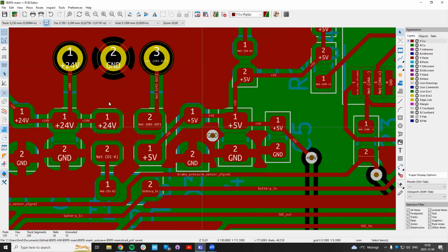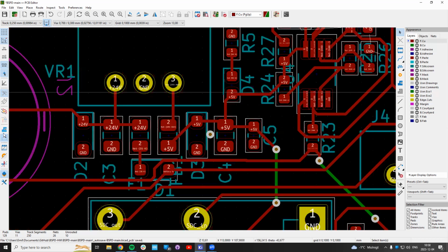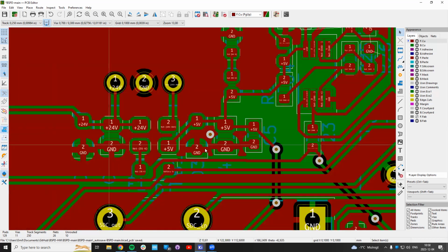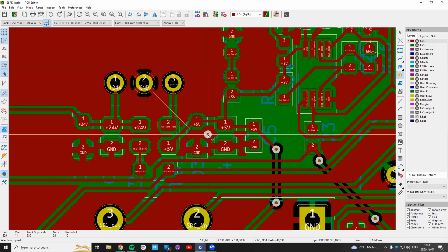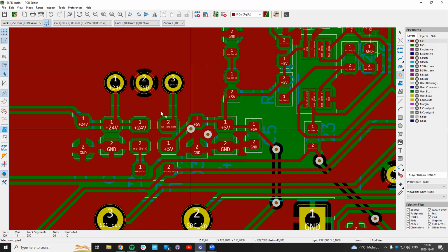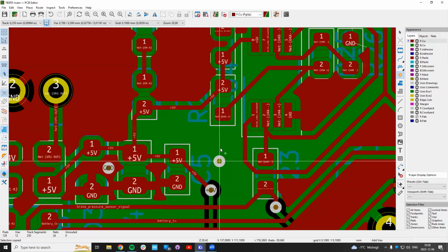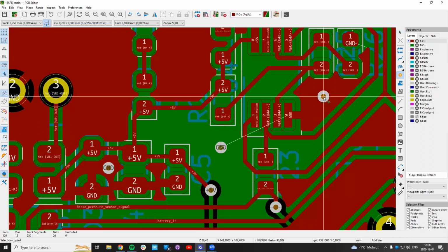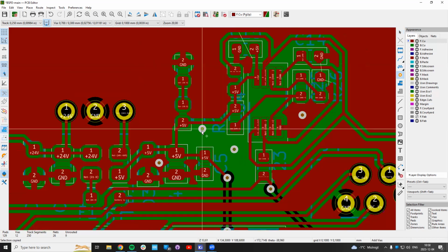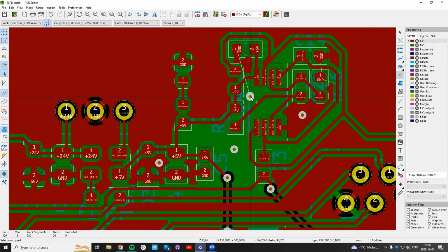Now, let's see, what happened to the white line? Did it disappear when I placed it? Yeah. This white line, as soon as I place this, it disappears because now there is a connection in between there, and I press build again. And you want to have grounded areas everywhere. So you see, I'm just going around. I'm seeing these large green areas.